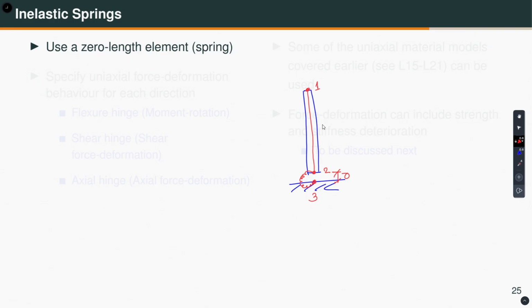Okay, that models my plastic moment rotation or inelastic moment rotation response. What about the axial direction, the shear direction? Well, I can make them constrained with equal degree of freedom, which I will demonstrate in the next lecture.